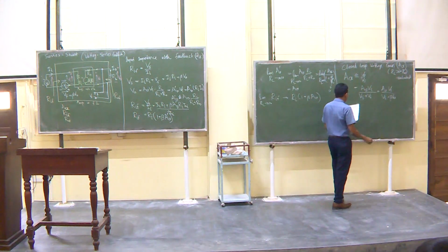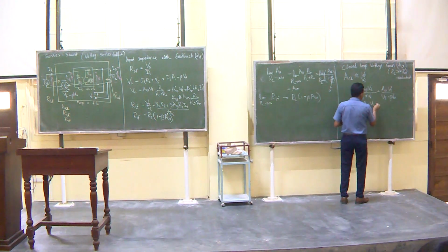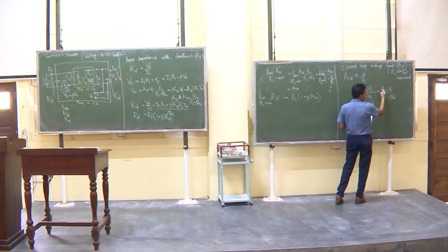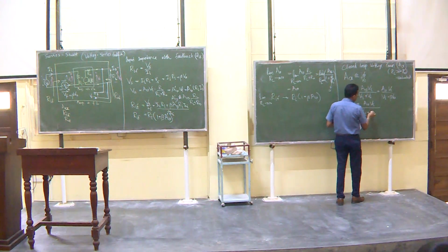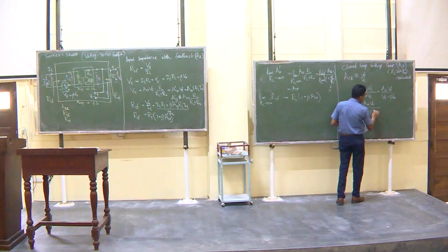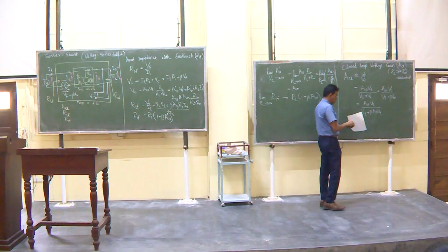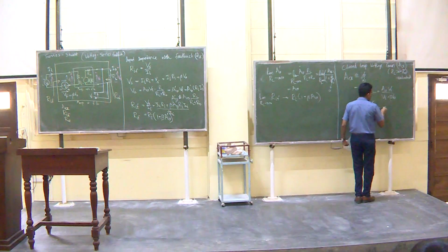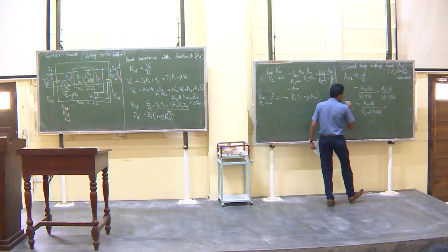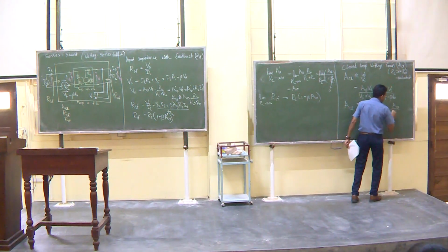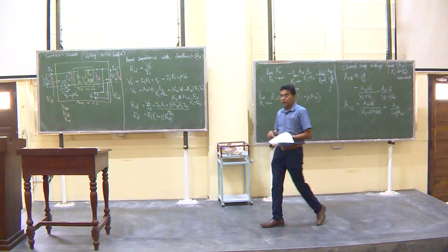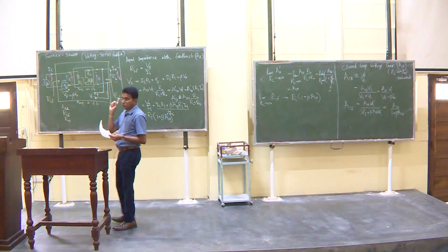That's also equal to AV Vi divided by Vi plus beta V naught, and V naught is AV times Vi. So beta AV Vi. Therefore, you can get rid of the Vi terms and you end up with A closed loop is equal to AV over 1 plus beta AV. That's the expression that we had last time, keeping in mind that this is for an unloaded condition.